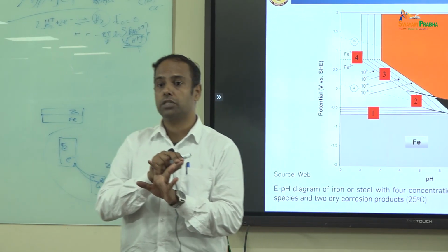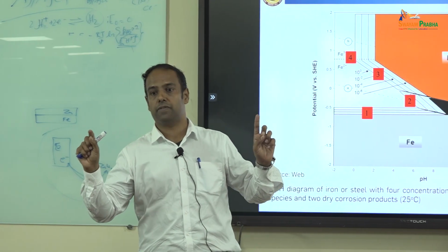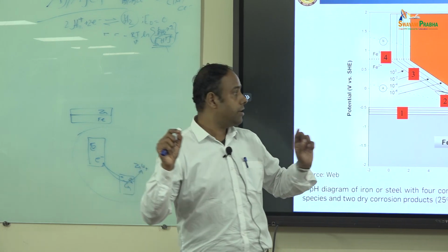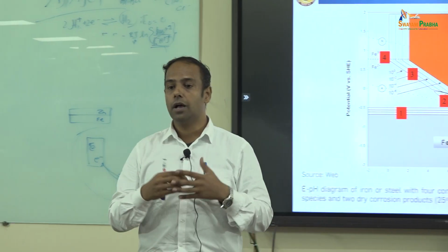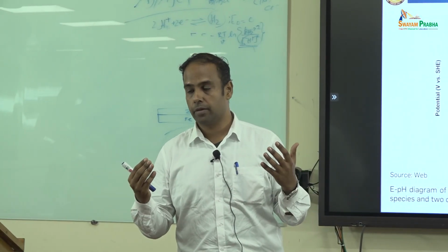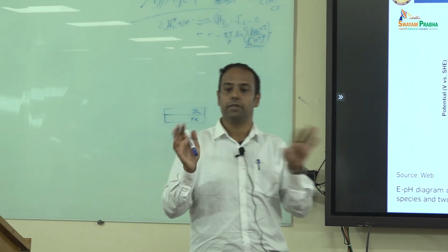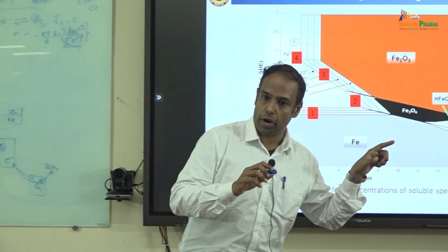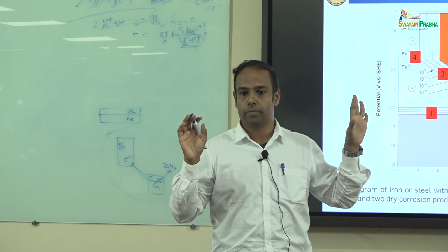The Nernst equation is what I need to use to fix the potential with respect to concentration of species and temperature, and that gives again E only. Then you get the Pourbaix diagram as the base to read corrosion for a metal-water system, right. And thermodynamics is only the feasibility. You can't say it corrodes at rate 10 or rate 20. It gives only that it will corrode or not corrode.